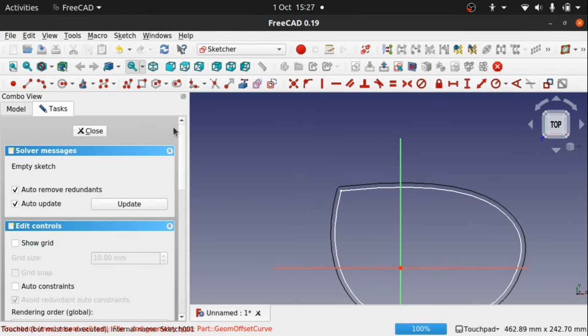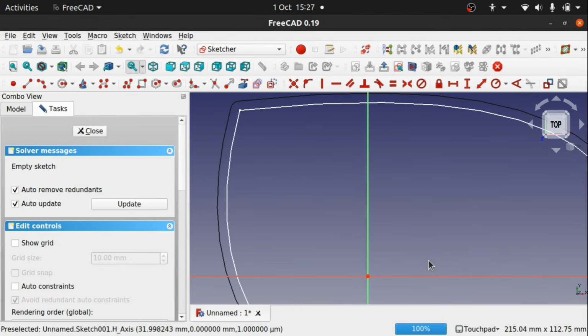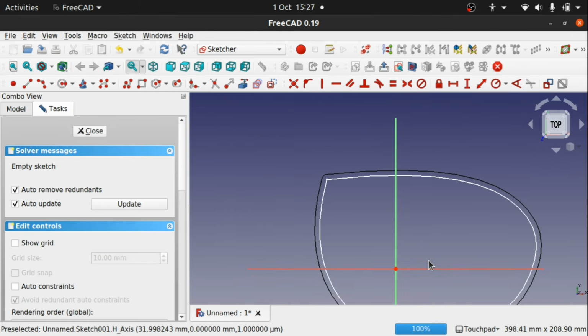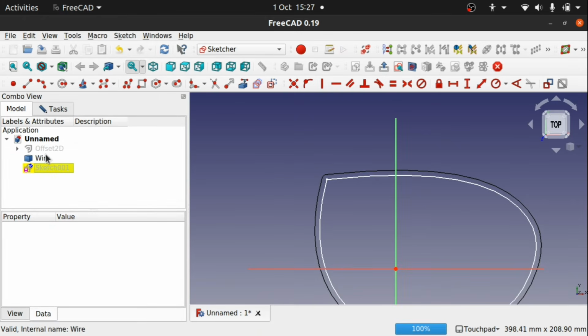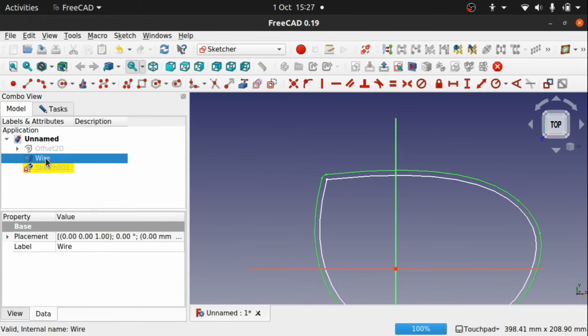And sometimes this will work and sometimes it won't. As you can see, it hasn't worked here and it hasn't created a sketch for us. We've got nothing in this sketch and we did have an error that came up. So we have to be wary of this, that if we're using B-splines we actually approach certain problems. Sometimes these can be fixed and the Curves Workbench allows you to fix these.